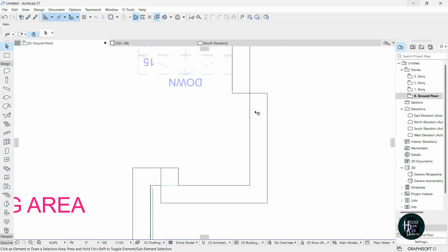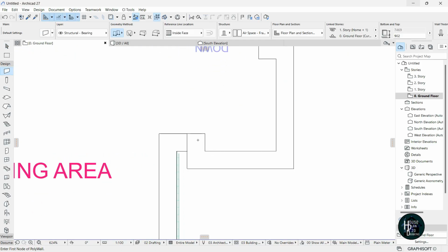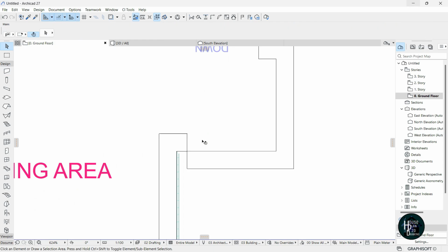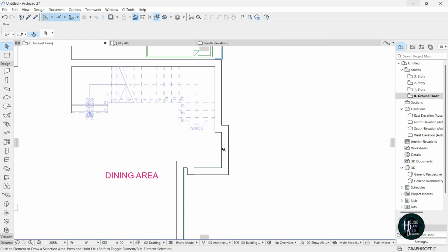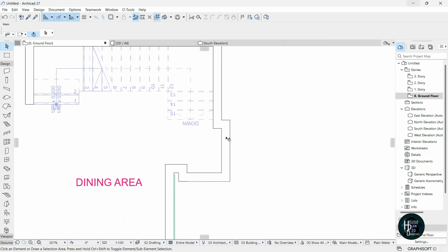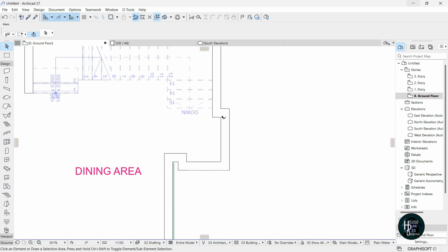and delete it. Okay, now hold on Alt, select this, click this to connect this one and double click. Okay, click this also, delete it. Hold on Alt, select this, click this edge to connect this side like so. So you're going to be having this shape come outside like this. Okay, so now we want to come and fix the curtain wall on this side here.